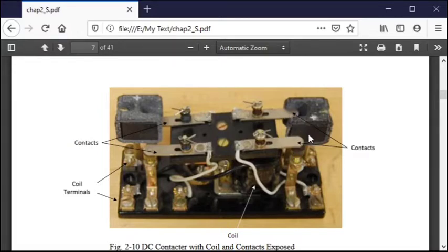And that's a typical application of a relay. It's a special application of a relay, but these are arc chutes that keep that arc from running around and doing harm someplace else in the circuit. You would never use a standard relay for this application, whereas they do exactly the same work. You energize a coil, it pulls this down against a spring, and you would see that these contacts, when they open, could have an arc, and at that point in time you want to protect them.